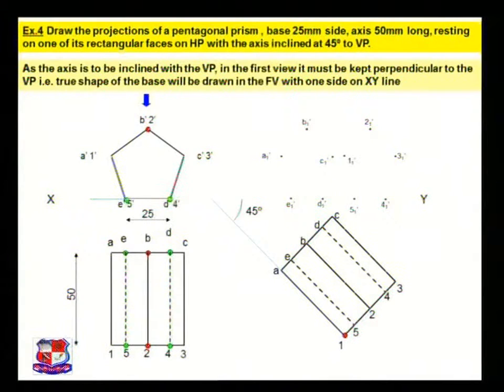Now as we are looking from here, this point 1 is visible, right? This is the visible point. So here point 1 should be joined with the full line. Join 1, 2, 1, 5 with the full line and 1A with the full line. All the rest of the lines would be dotted lines, and the lines which are outside lines will be full lines.